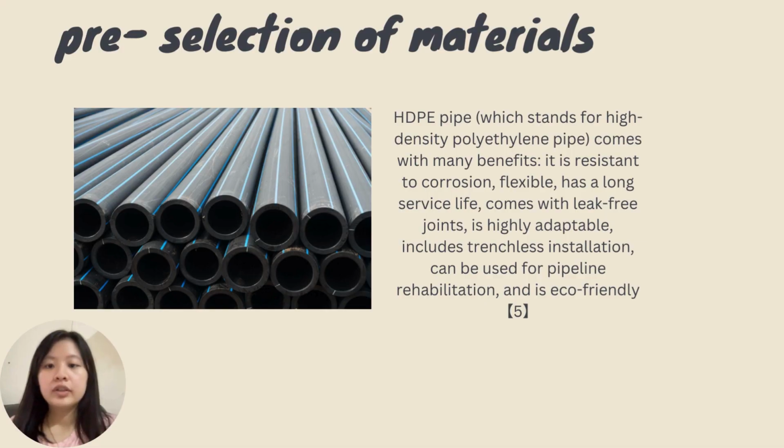So for the water storage tank to the swimming pool, the pipe we use is polyethylene pipe, or you can also say HDPE pipe. The benefits are that it is resistant to corrosion, flexible, and has a long service life. It comes with leak-free joints, and it is highly adaptable. So it's very suitable in this case, as it can resist corrosion and is very long lasting.